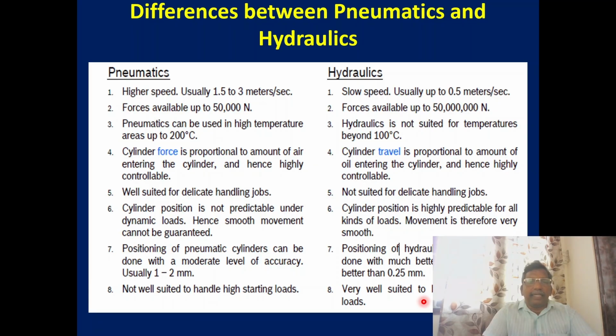When comparing pneumatics and hydraulics, when you need a high speed system with low force, you can go for pneumatics. At low cost, you can go for pneumatics. But for high force, a high precision system, and slow speed, we can move to the hydraulic system.